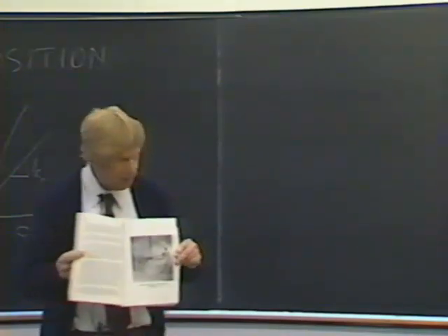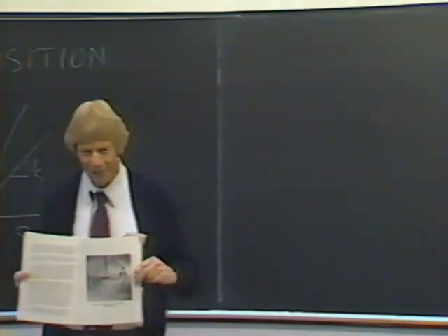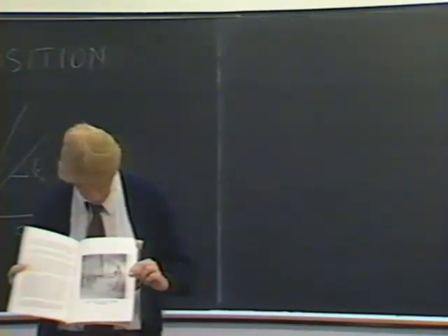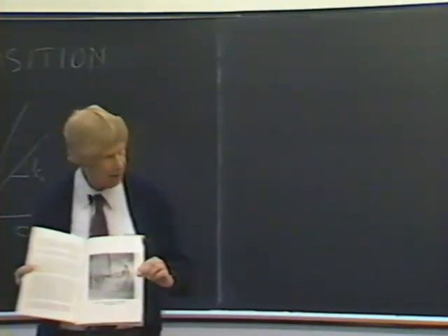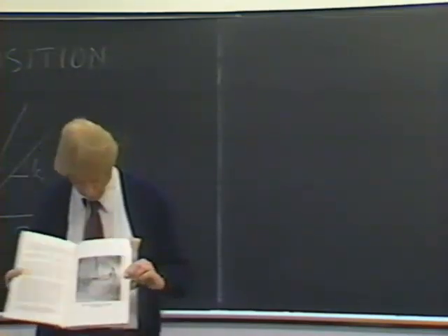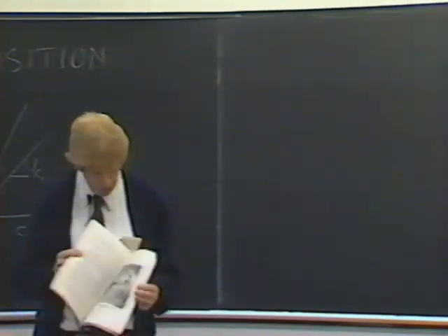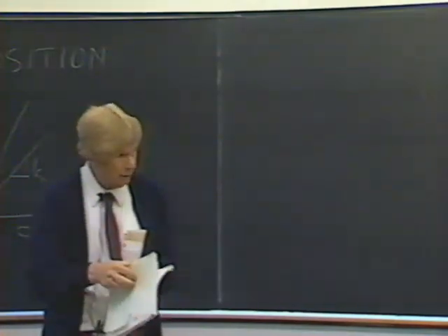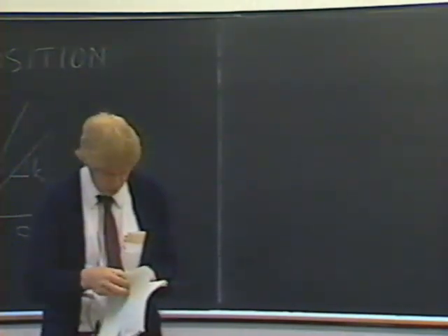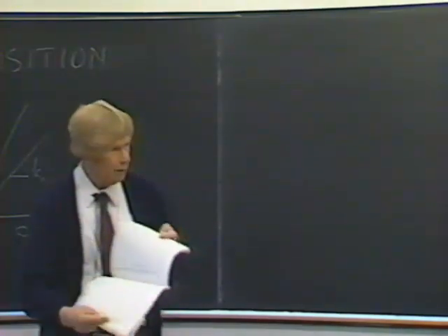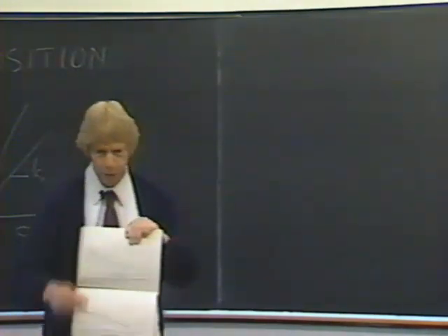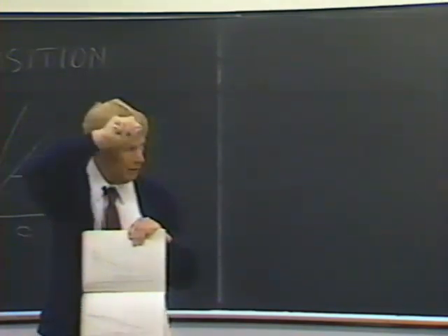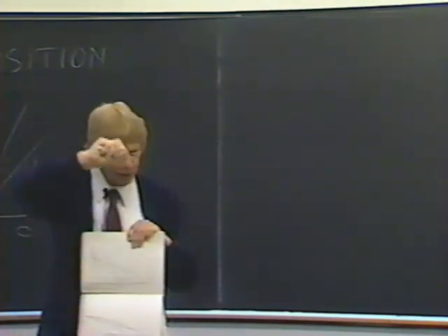The results of those measurements are shown, and what we measured was the force necessary to push the penetrometer into the mud. We did that with a laboratory triple beam balance, mounted on a support so that we could lower the balance and determine the force as a function of depth. If you'll notice, there are a lot of curves on page 72 that have kinks in them, or knees if you like.